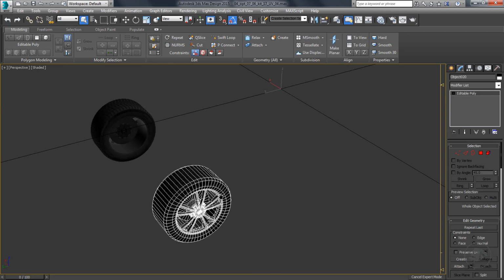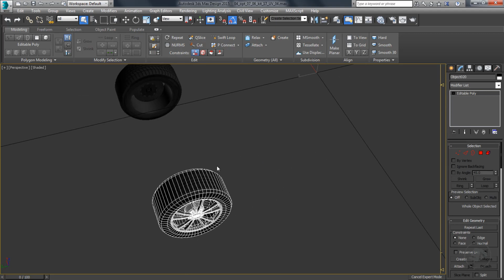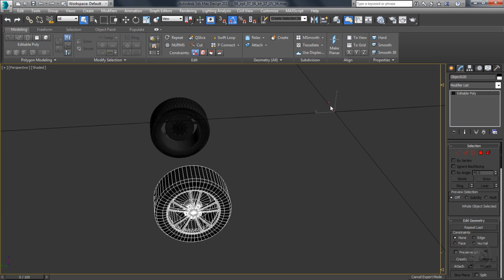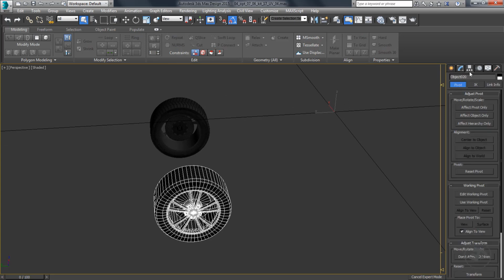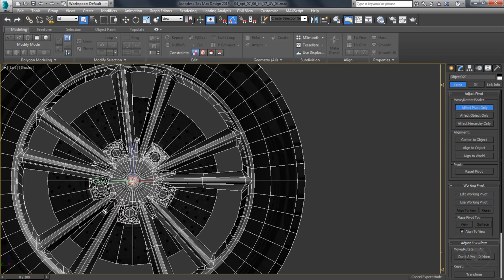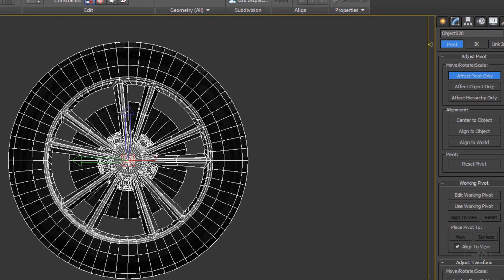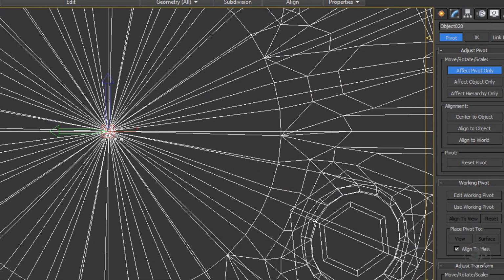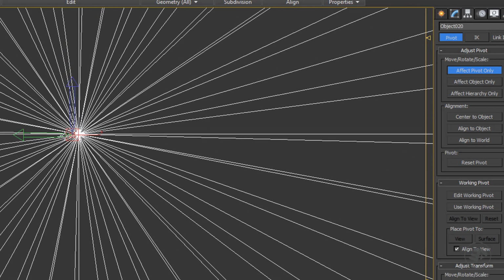In either the one wheel or the four wheels scenario, we need to mark the location of each wheel spinning center. Before exporting this project to the game engine, we need to align all objects pivot to the world center. This will preserve the locations of all objects as intended inside the game engine. However, inside the game engine, we need to align each wheel pivot to its parent dummy. The pivot in this case will be used as reference to apply animation on the dummy children.